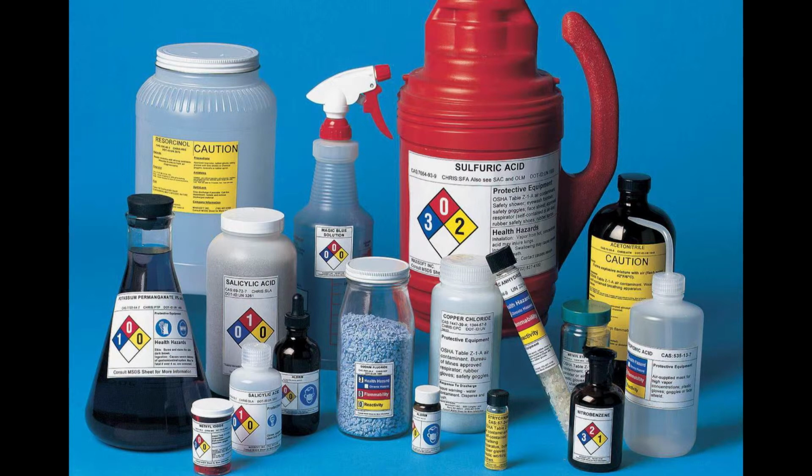Labels on portable containers. If a chemical is transferred from a labeled container to a portable container that is intended only for the immediate use by the employee who is going to make the transfer, no labels are required on the portable container. However, if the employee leaves the container unattended, or if the portable container still contains a hazardous chemical at the end of the work shift, the HMIS or NFPA labeling system and the product identification must be placed on the container.